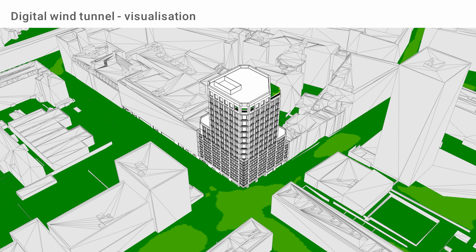And then when the level of the project develops, when it becomes more detailed and more refined, then you can also bump up the level of detail of your simulation, and you can look at structural loading, let's say, as well. And with the idea that when you look at loading in the early days of a project, you get a better feel of reducing loads, because if I'm comparing codified loads with wind tunnel results, there could be a drop of 30, 40, 50% sometimes. So to know that early on is super valuable, and it can help the design of the building go forward another step.